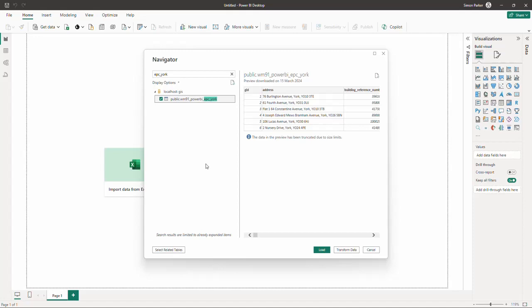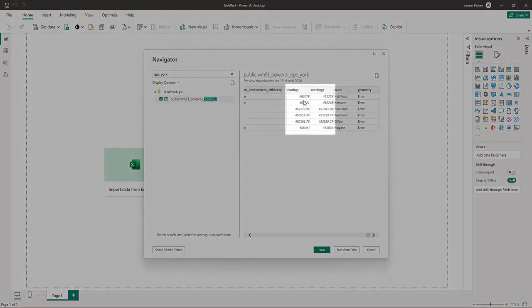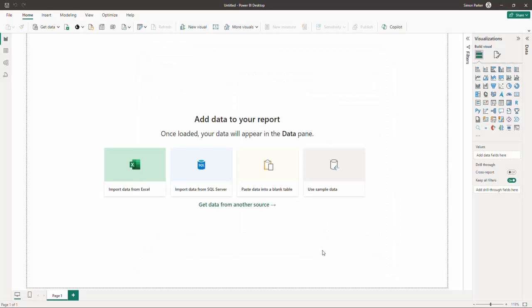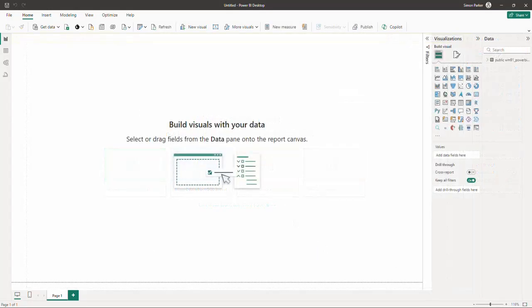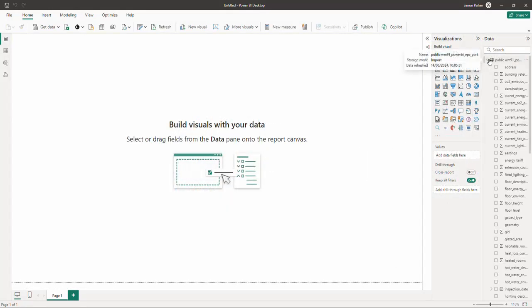To visualize the data on the embedded map, the data needs to include coordinate information. For point datasets, you need either OSGB eastings and northings or latitude and longitude coordinates. At the end of this specific dataset, we have two separate columns displaying the eastings and northings for the data. If you wish to display line string or polygon features, you need a column containing the GeoJSON description for these feature types. The Cadcorp Online Help provides instructions on how to prepare your data for Power BI. I'll now select Load to add the data into Power BI. We can now see the data is loaded into Power BI.